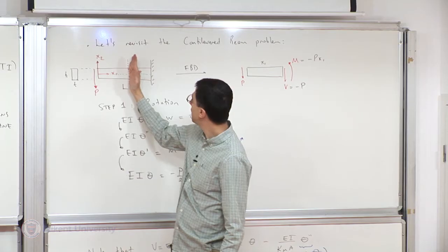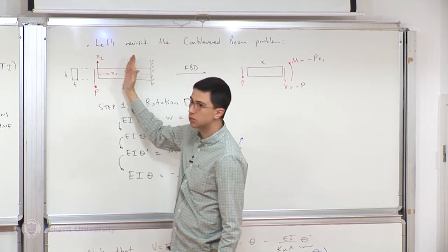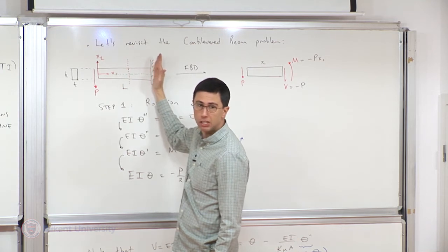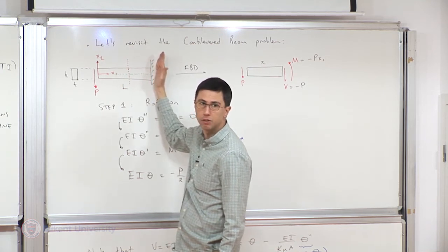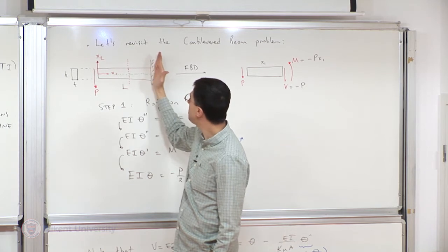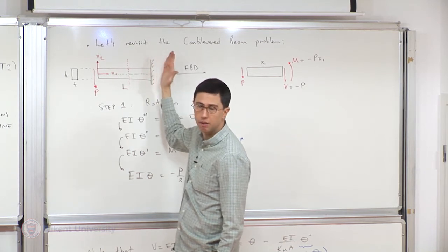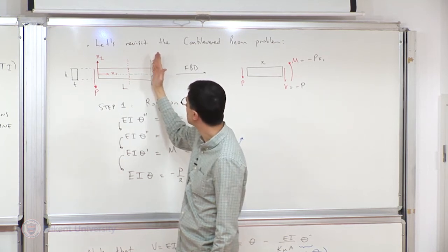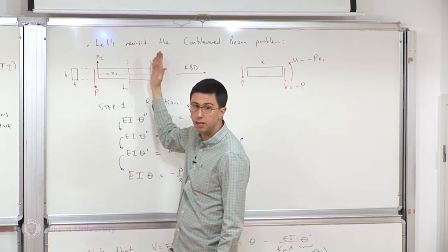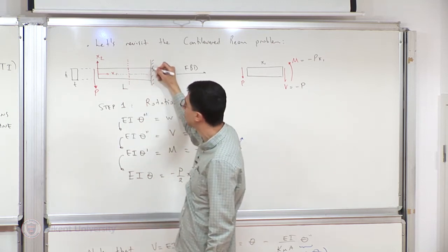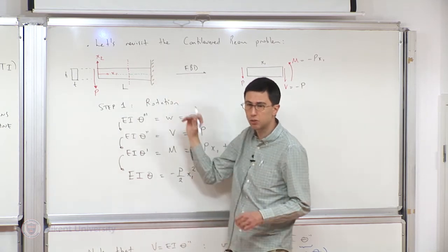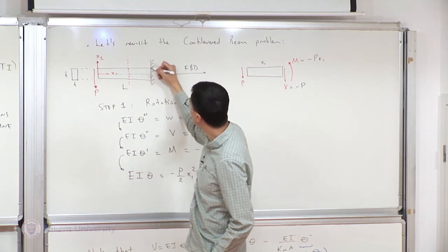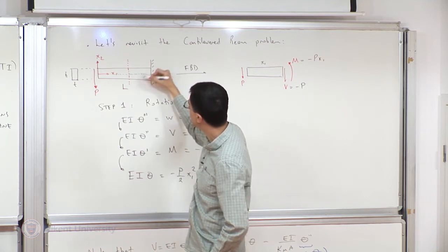The rotation describes eventually the rotation of this cross-section. Now, where the beam is attached, that cross-section is constrained from rotation. So I'm going to say that the beam does not rotate at the point of support, which is x1 equals L. That's what we always used to do in ME231 as well. But remember, that's also what I've done in the analytical solution, not at every point, because there were too many requirements to enforce the fact that displacement was essentially constrained along the whole vertical line at x1 equals L.